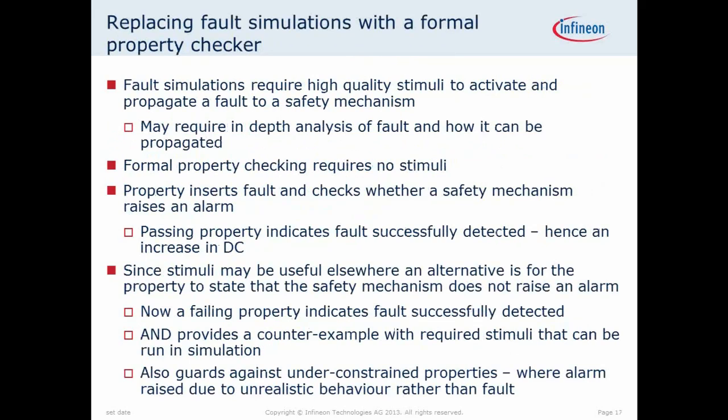Okay, so the third strand of what we did was to try to replace the fault simulations, which are extremely time-consuming and quite effort-intensive, with a formal property checker. So fault simulations require high-quantity stimuli, as I said, to activate and propagate the fault to a safety mechanism.